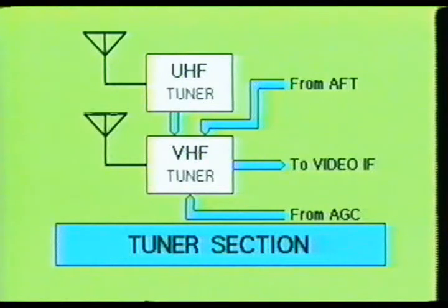As you can see, tuner defects can create a number of symptoms within the receiver. These defects may be caused by a component which has changed value, a failed component, poor solder joints, or poor connections at the input of the tuner stages.